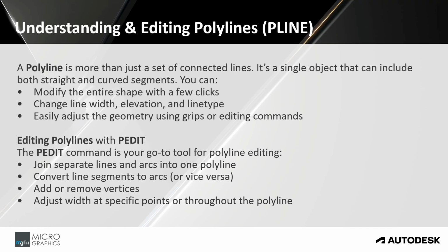Editing polylines with the p-edit command. The p-edit command is your go-to tool for polyline editing. Join separate lines and arcs into one polyline or object. Convert the line segments to arcs or vice versa. Add or remove vertices and adjust width at specific points or throughout the polyline.